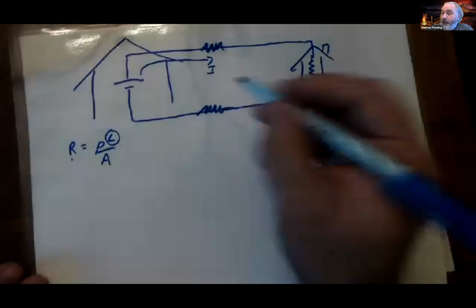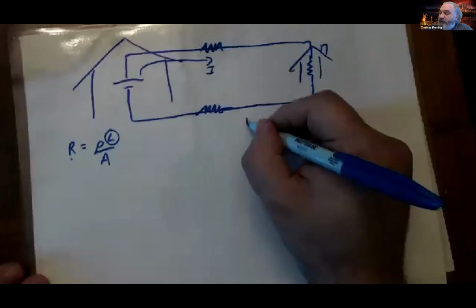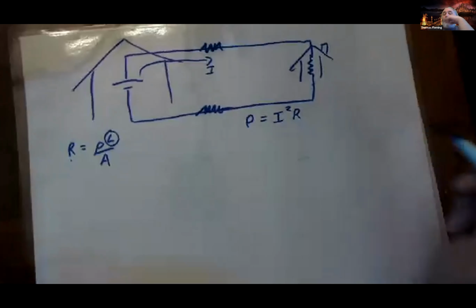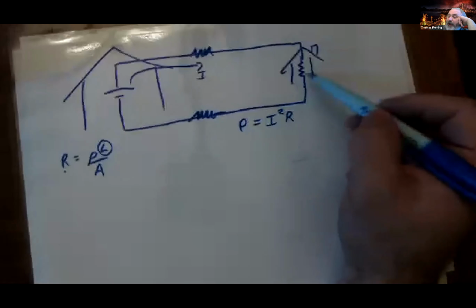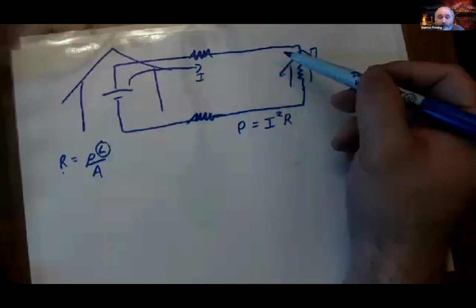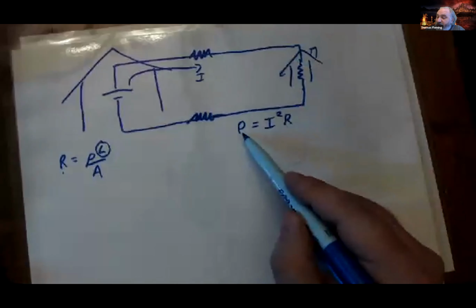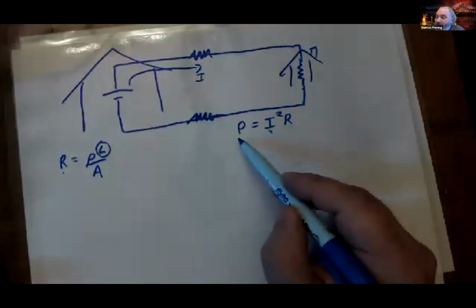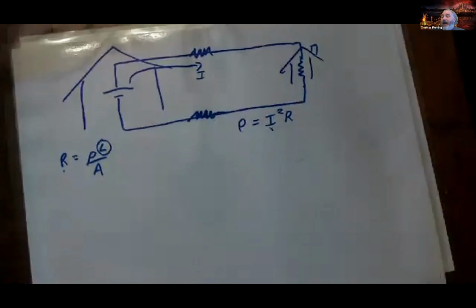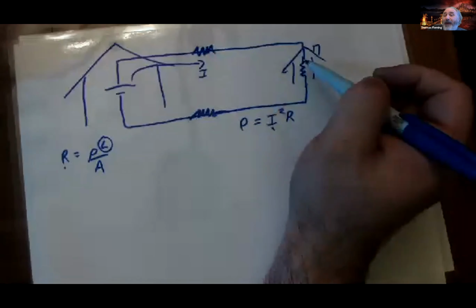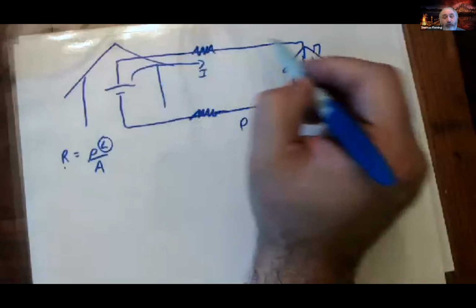How much power? Well, we had 3 formulas for power, right? But one of them was power equals I squared times R. And remember, since all the current for the entire house, or heck, for the entire town, has to go through this section right here, the power that it takes to just get it through here is I squared times R. Every time you double I, you're quadrupling how much power it takes. It's taking a ton of power just to get it through the power lines. And that's not power that the house can use. That's power I'm wasting just getting the energy to you.